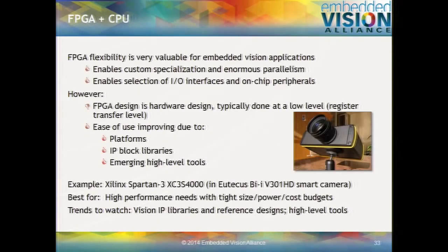Also, FPGAs are starting to be used as compute engines in these kinds of applications, and that's becoming more feasible now that there are ways to implement algorithms on FPGAs that don't require going down to doing register transfer level hardware design in Verilog or VHDL. For example, high-level synthesis tools that allow you to take algorithms expressed in C or C++ or SystemC and synthesize RTL, or OpenCL, like I mentioned a minute ago.